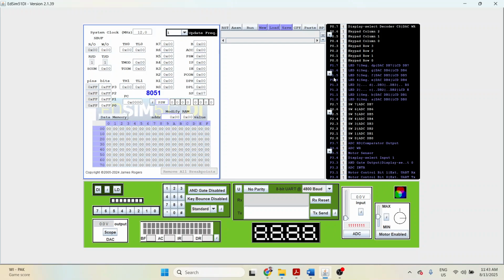Now what is a port and all, we will see when you observe the 8051 microcontroller. After that there is a particular section where all the registers along with the memory sections are given. If you observe here, there are two types of registers, general purpose and special purpose. R0, R1 up to R7 are the general purpose, and the special purpose are SP, DPL, DPH, PCON, IE, IP, PSW (program status word), accumulator, and register B. All of these are the special purpose registers.